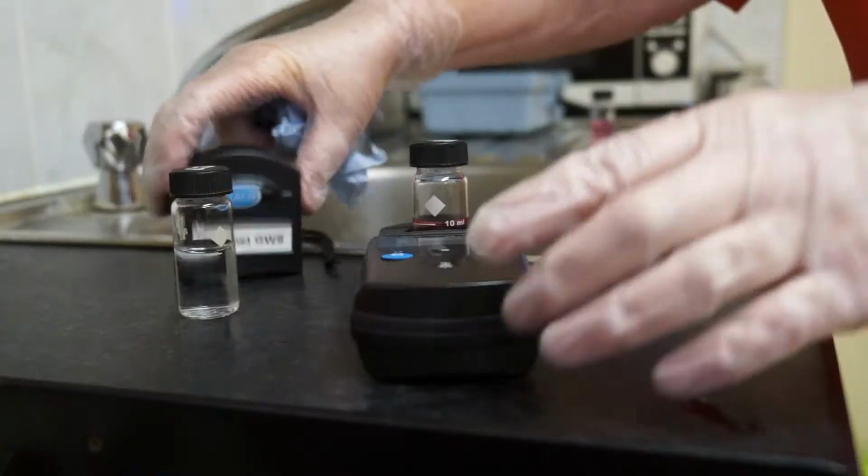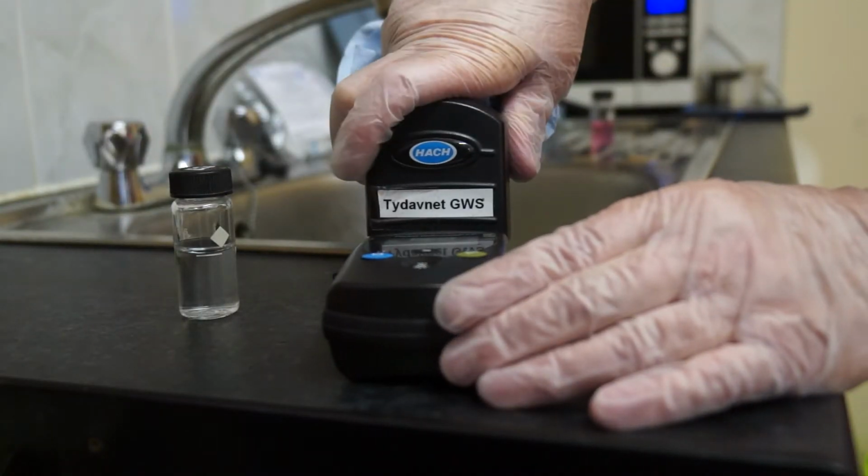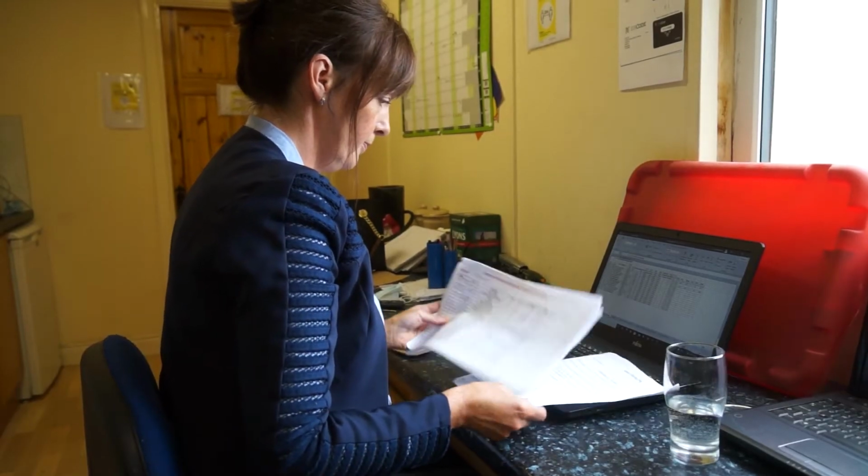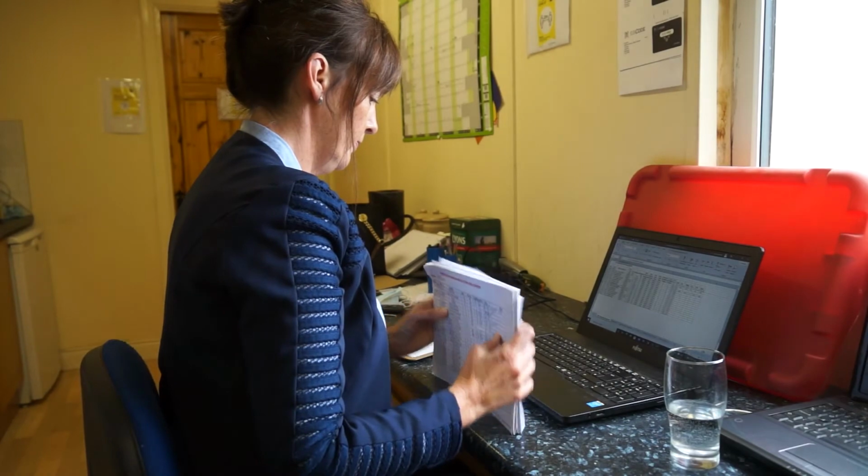We also notify our water services body in the local county council. We have a turbidity monitor and a chlorine monitor, and we check that those are in full working order before we start the process, that they're calibrated, the batteries, and all is in place before he sets off for his flushing.